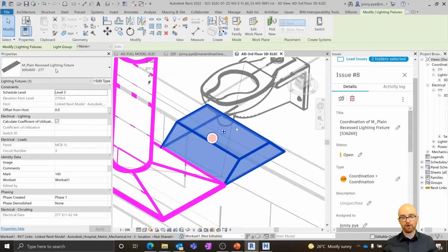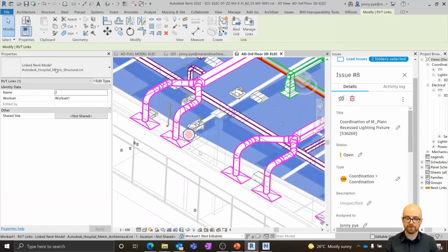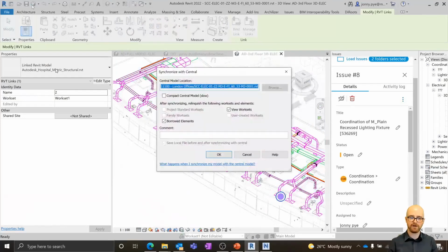If you've got a Navisworks workflow, you've got a bit more control in Navisworks in terms of what you want to clash together. And as you've seen inside of the Model Coordination side of things, it uses Revit 3D views, and the states those views are in, to decipher what elements you're going to be clashing against each other. So we picked up those two pins, we've made the changes, and it would be exactly the same process now for pushing those changes back to Autodesk Docs.